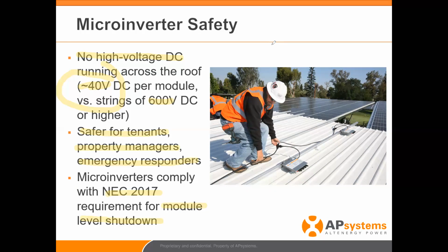Yeah, Chris, I think this photo in particular is a great application example, because this was a carport application down in Fresno, and they specifically chose microinverters because they didn't want the string inverters at the bottom of the carports, accessible to the public potentially. Otherwise, they'd have to build one of those wire cages around it, and just the aesthetics of that was awful. So, yeah, micros are a good alternative to that for carports.